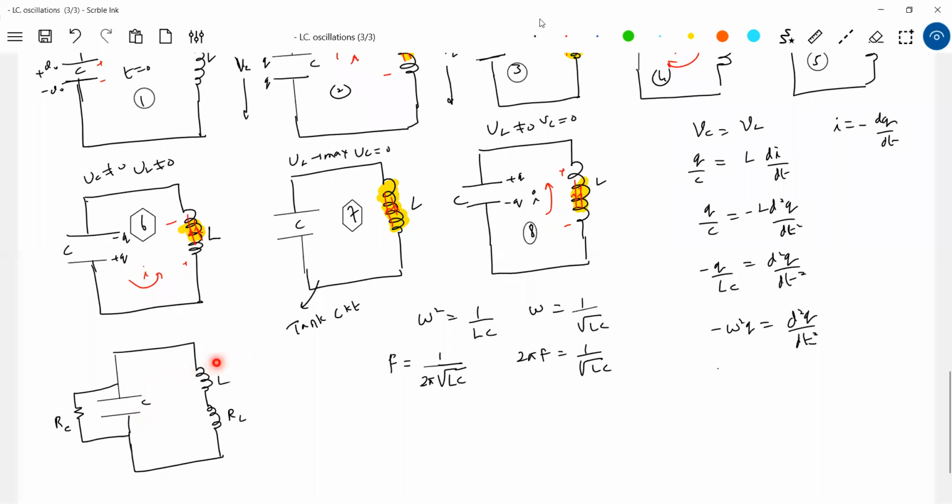From here, I'll put a mutual inductor. With that, I'll take back that oscillation energy. Like that, I can generate an electrical signal of desired frequency. By adjusting the values of L and C, I can generate an electrical signal of desired frequency. They may test you with this one. This is a practical LC oscillation circuit. We'll just confine to the ideal case. This is a practical one. This is due to resistance of the dielectric slab. This is due to the inductor RL.